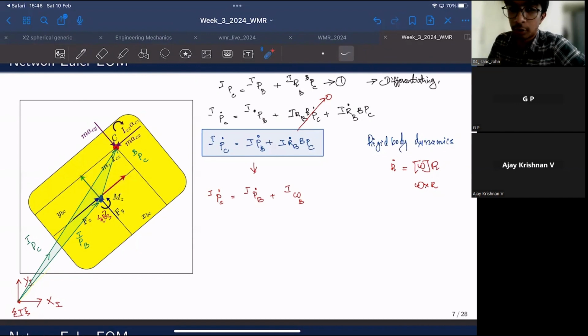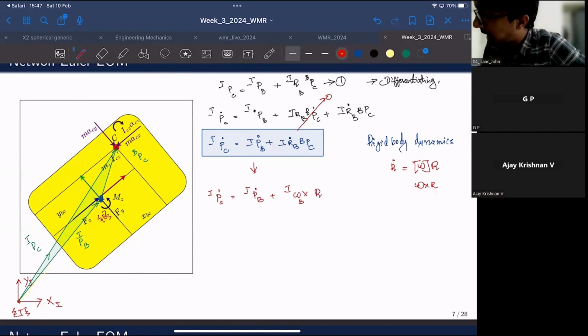The mobile robot would be rotating with respect to this inertial frame of reference. This cross, we also have this term, R dot will be omega cross R. We also have this term R, which in this context will be the rotation matrix of body frame with respect to the inertial frame. Then we also have the position vector of C with respect to B.